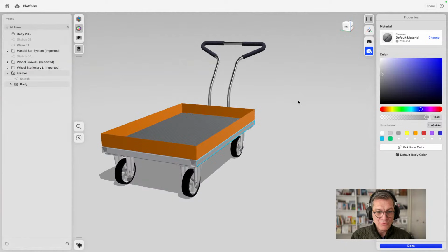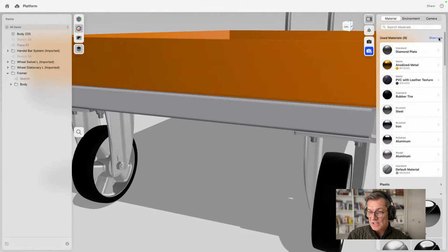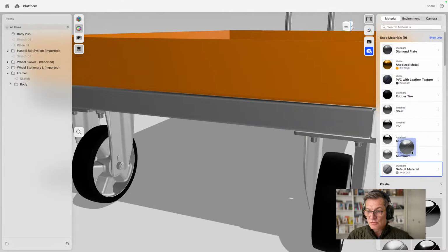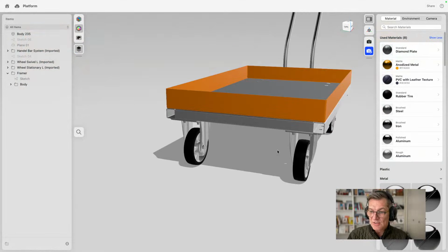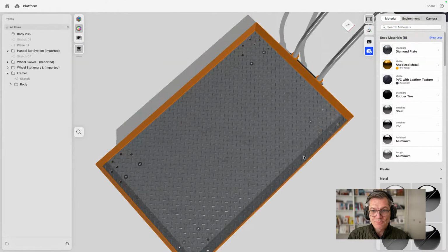This has a default material. We use primarily steel, so the default material for these tubes will be steel extruded. So the brush steel I have, I simply drag onto the default material that is representing only those square tubes I created. Then the material is also updated.